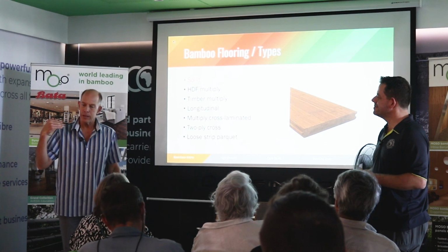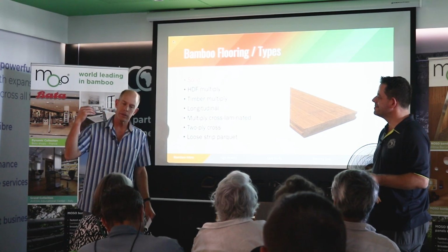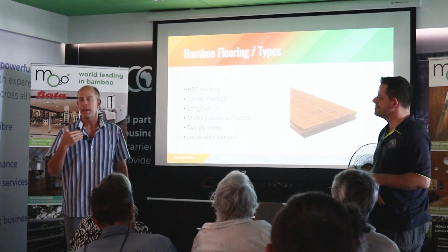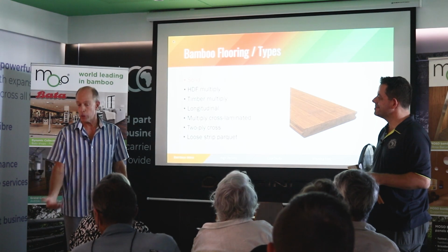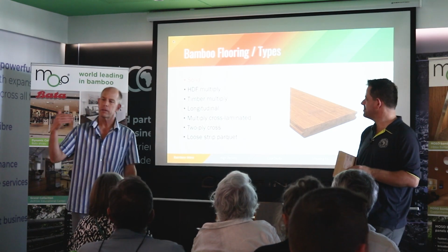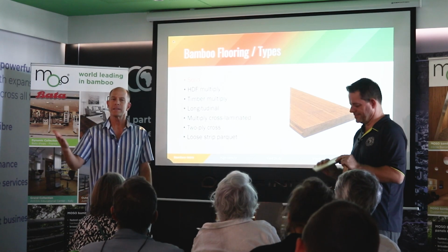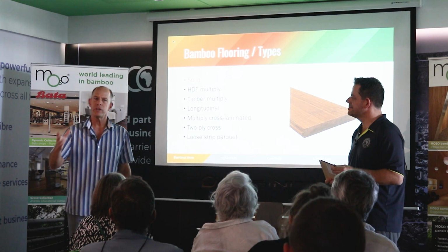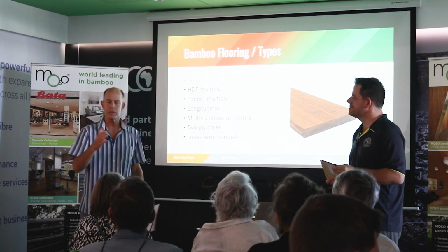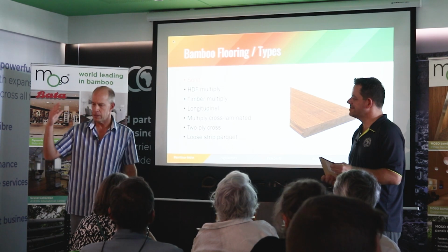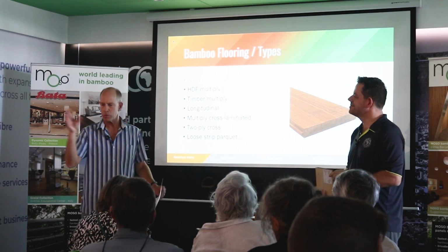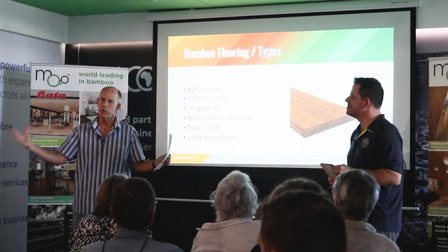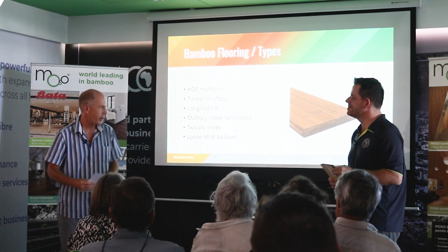As far as installation goes, you can install it as a floating floor, you can install it glued down, and in some applications you can install it onto joists too, depending upon the thickness of the flooring, depending upon the subfloor. So once again, as I say, it comes back to the installation being very critical. It's not just your flooring. You must look at where it's going to be installed, what the conditions are, what the flooring is, what the budget is. So a successful floor is combining all these things in the right way.